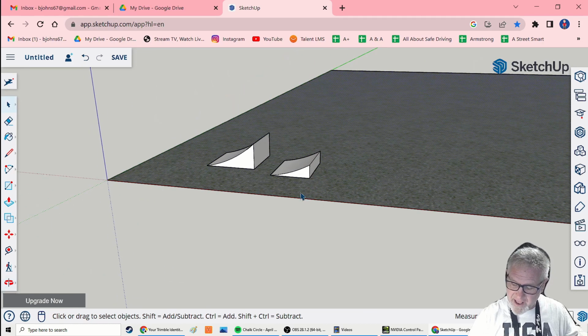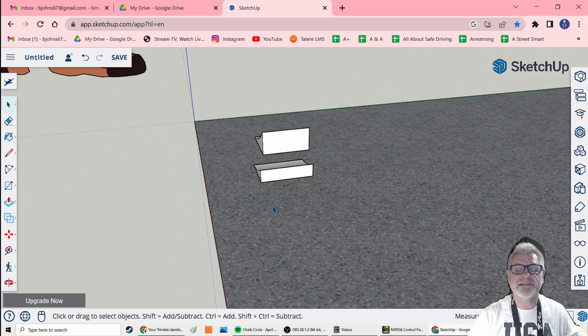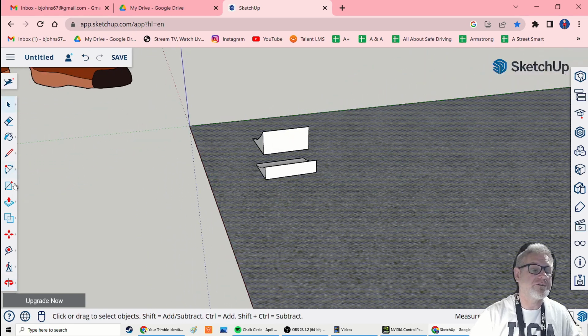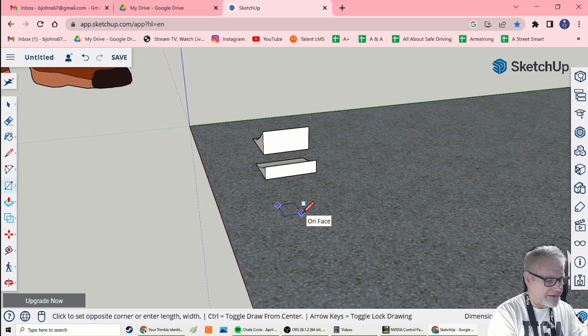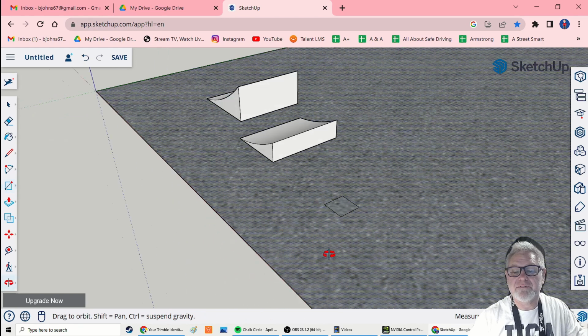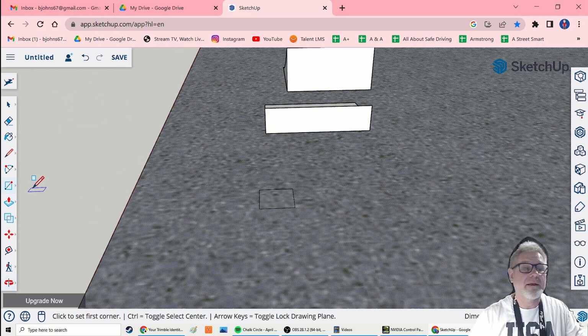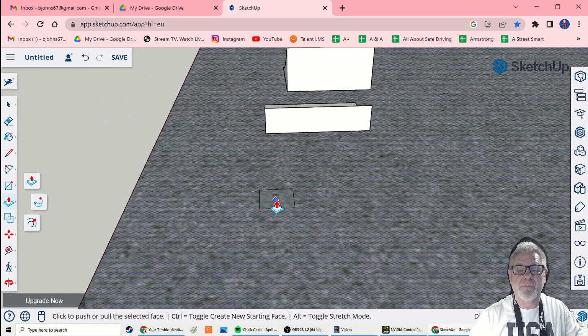So next up, I have a flat rail. So this one's going to be a little bit trickier because we've got 2, this might be squares. There's quite a few pieces here. So we want this to be a square. So let's go ahead and just go 25 mm, comma 25 mm, enter. That'll give us a 25 millimeter square, and then we can pull that up. Make sure it's highlighted first. Click it. There you go. And then pull it up. Probably something like.